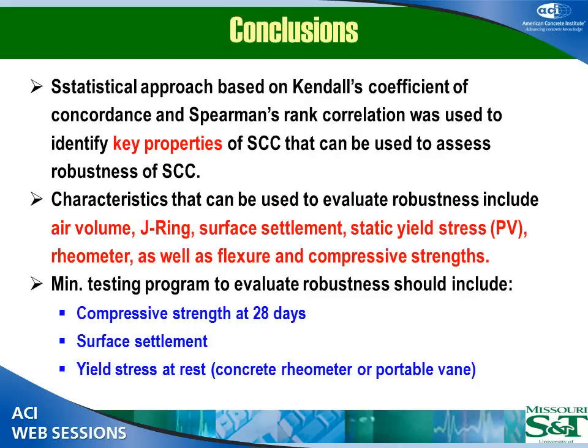In trying to further understand your conclusion that the PNS seems to be a bit more robust than the PCE, is it perhaps because at a given yield stress, same water-cement ratio, the PNS is giving us a higher viscosity than the PCE in your particular mixtures? I'm just trying to further understand why that's the case.